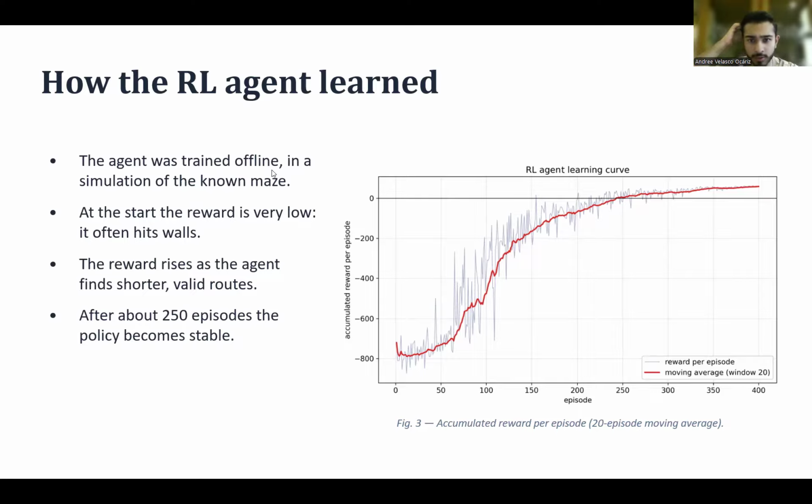From the vision side, this also meant the calibration had to be accurate. If the pose is wrong, the safe execution of the policy breaks. We had to validate that our kinematic model reached an error of only 2.7 centimeters before we trusted it. The clearest physical limitation was a lateral slip of about 8 to 9 centimeters in each in-place 90-degree turn. The camera let us measure this very clearly, run by run, and it was the largest source of error.